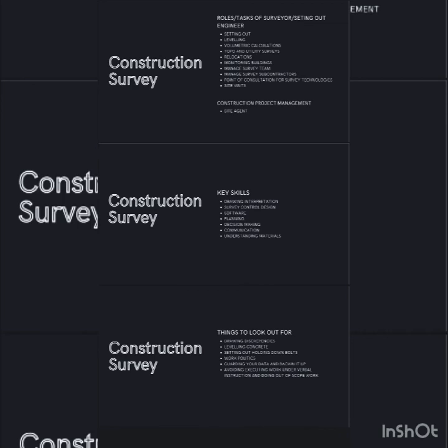Then all the data that you work on, the control designs, the setting out data that you create using the software, please back it up. Work machines also die. The total stations that you check the data on might be at fault, and they need to go get fixed. It might take long, and there's data there. So every time you do a job, please back up your data. Back it up in your computer, back it up in your cloud drive. Your computer as well might crash. Anything might happen, so you have to have multiple streams of backup.